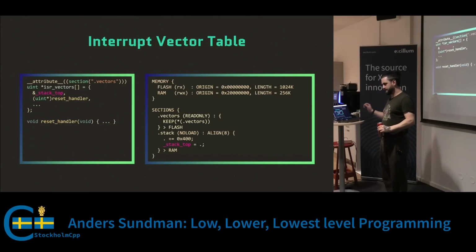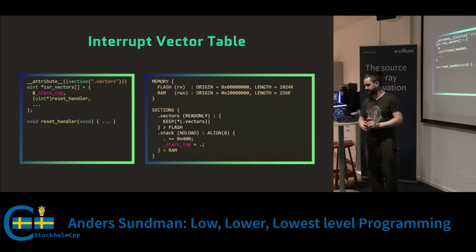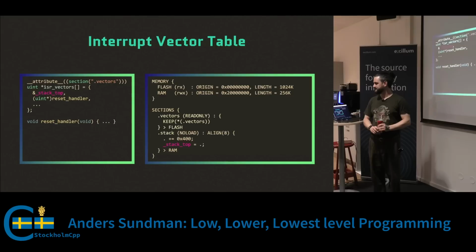Why not assume that the reset handler will set up the stack pointer as its first instruction? It's just not done that way. I don't know why. Ask ARM. Maybe someone knows, but I don't. A lot of architectures don't do that for you, but ARM Cortex does set up the stack.